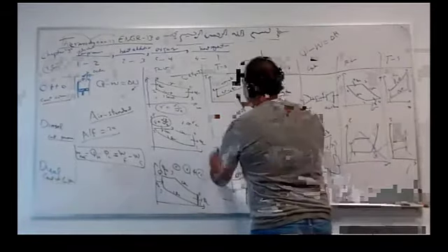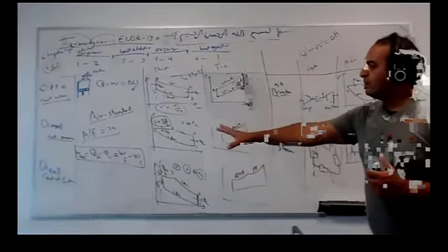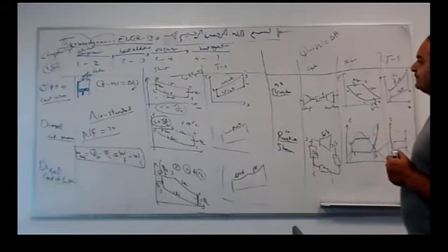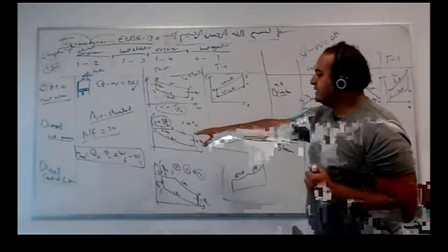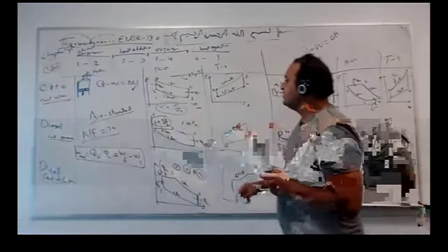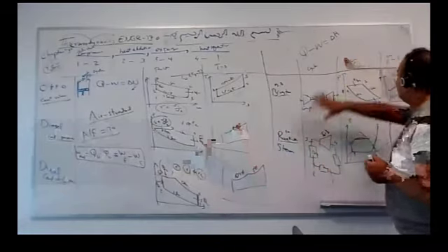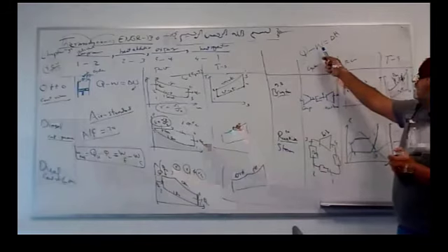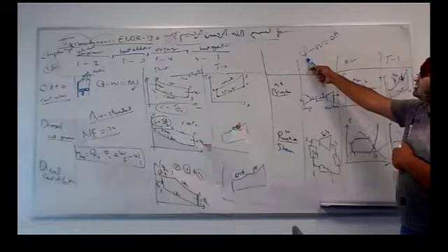Compression, expansion, compression, expansion, or power. Expansion means power. So here we have a closed cycle, Q minus W equals delta U. Open cycle, Q minus W equals delta H. Here, delta U is Cv delta T, unless Diesel at constant pressure, because we have work, it's Q equals delta H. Everything is either this or this. Work, like compression or expansion, you have this. Heat addition, you have this.